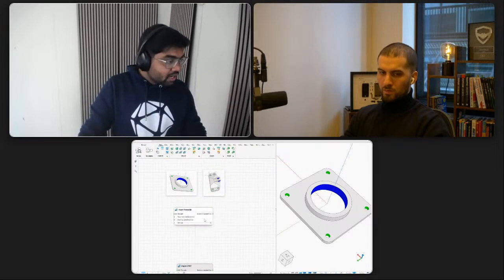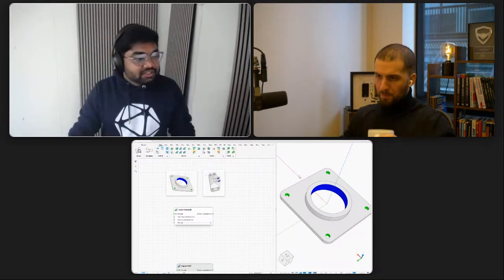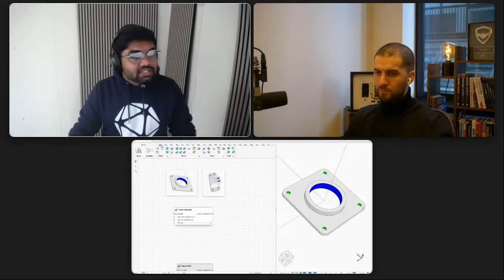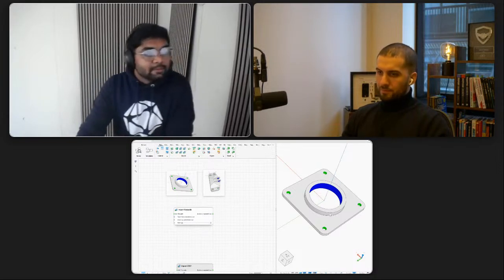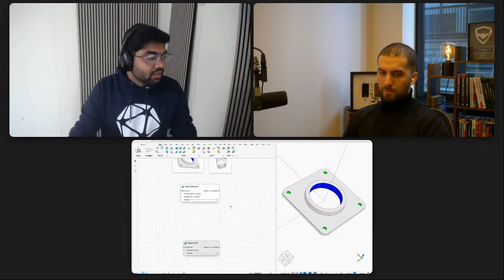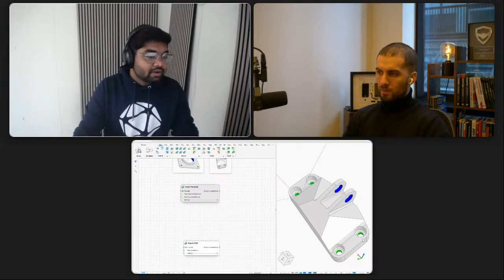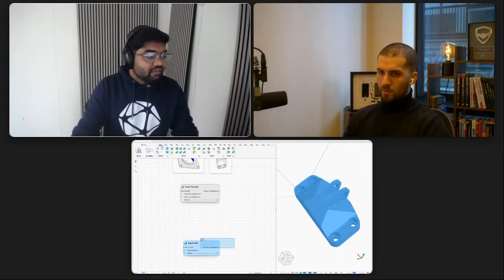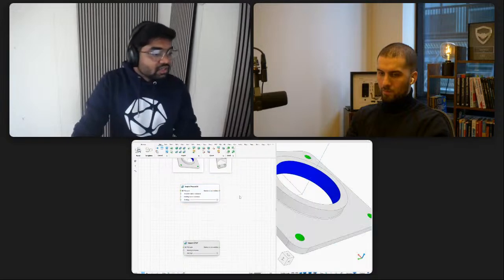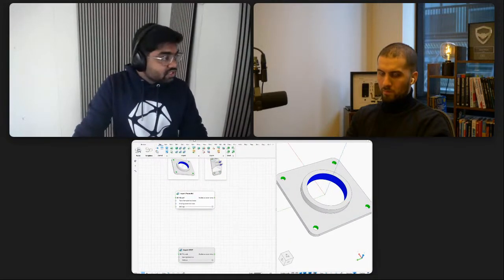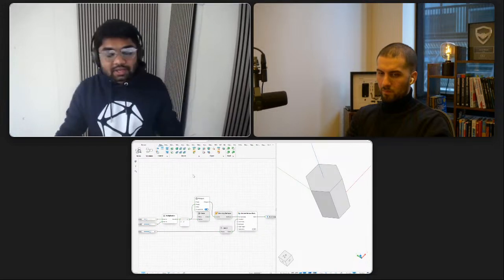So here we have a Parasolid part that we are importing to perform a linear static analysis on, where the regions colored green will be fixed. And then we apply a force to see how this geometry behaves under the loading scenario. We also have a different geometry, which has the same attributes, the same color data. And I will tell you why we use two geometries here and how it applies. Of course, the workflows I'm showing here can be made into a template in my library.